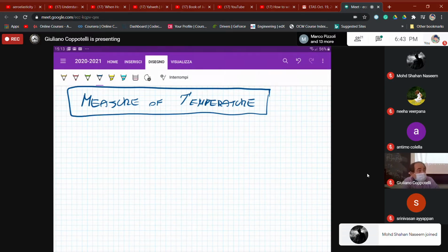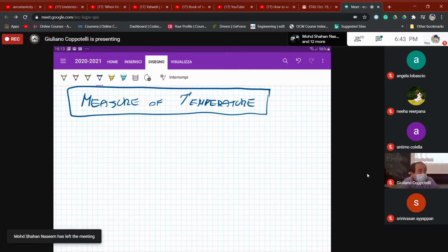Then we saw some applications of the strain gauges as devices capable of measuring other physical quantities, force, stresses, strain, okay? And we made a very easy application of evaluating the principal value of the strain, using the geometrical or analytical approach, and the graphical one, the more simple.